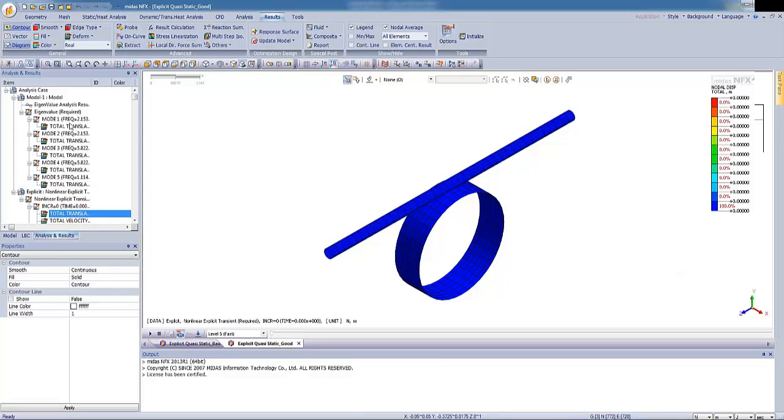First, natural frequency was close to 215 Hertz. And you can easily calculate the corresponding time period is 0.0046 seconds. And from this we can derive the velocity, and it will be 22 meters per second. So it has been estimated properly because this value is around 0.5% of the speed of sound.